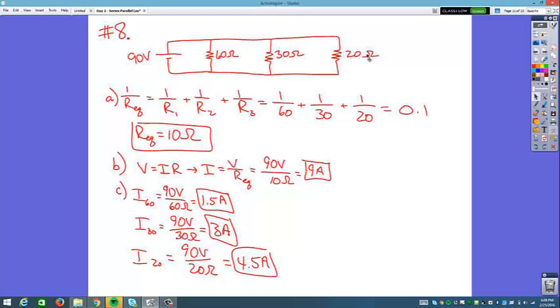With your parallel circuits, your voltage is the same at each one. Since each is almost like its own separate circuit, independent of the other ones, your potential will be the same for every resistor in a parallel circuit. Your current, however, will be different because current is based on the resistance. Since each one is separate, the current through every path is going to be completely different.